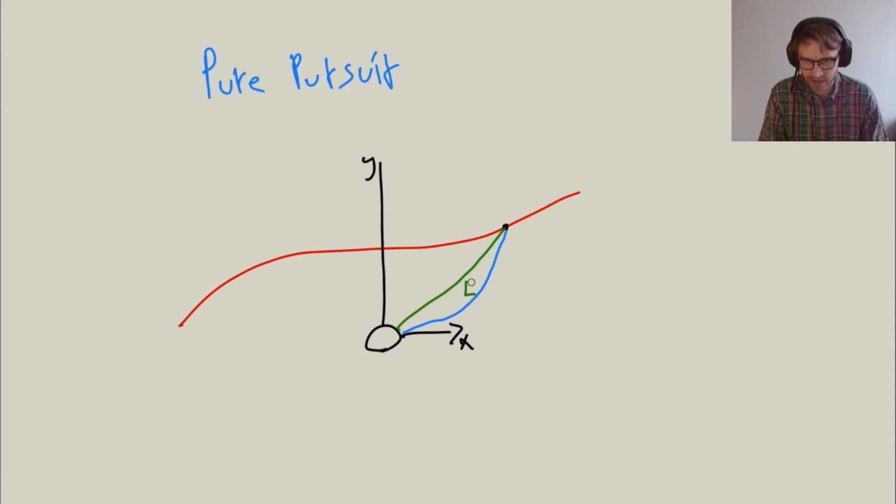And so the center point of this arc, so it's part of a larger circle, like this. The center point of that circle has to be on this part of the y-axis. So now we have the radius of that arc for a circle. And since this turtlebot center point is also part of this larger circle, this distance here is just as well the radius of the circle.